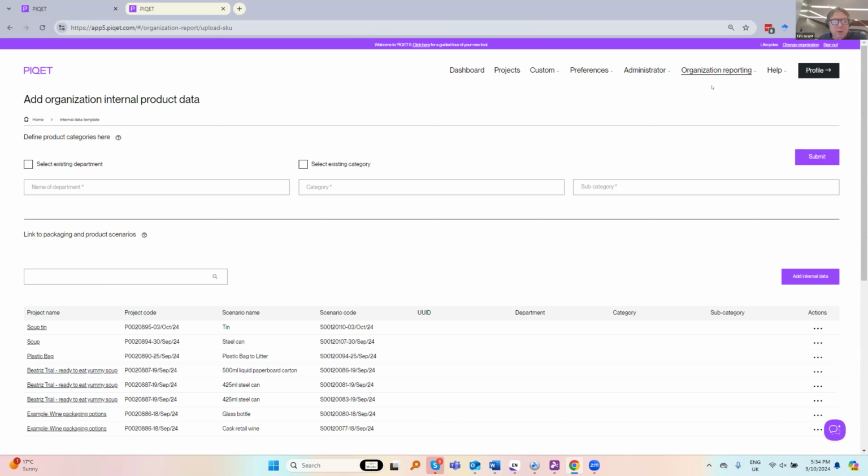Yeah, and the other thing we want to do with the certifications is, if you're certifying a material as being carbon neutral, then we want to be able to separately report the results of that footprint, including the carbon neutrality of that particular pathway. So under the ISO standards, you can't include carbon offsets and carbon neutral claims within a base LCA, but you can report it as a separate value.